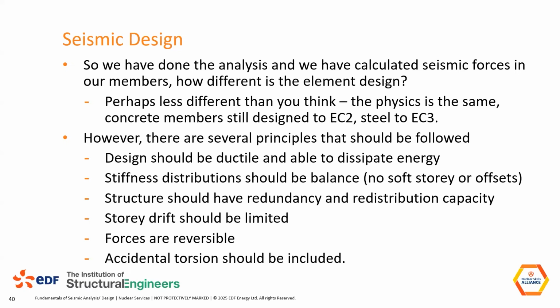There are a couple of additional principles we need to consider for seismic analysis, and the main one of those is ductility. Rather than just making the design stronger, we're trying to give the design flexibility, or have failure modes that are ductile, not brittle, and which can dissipate the energy.